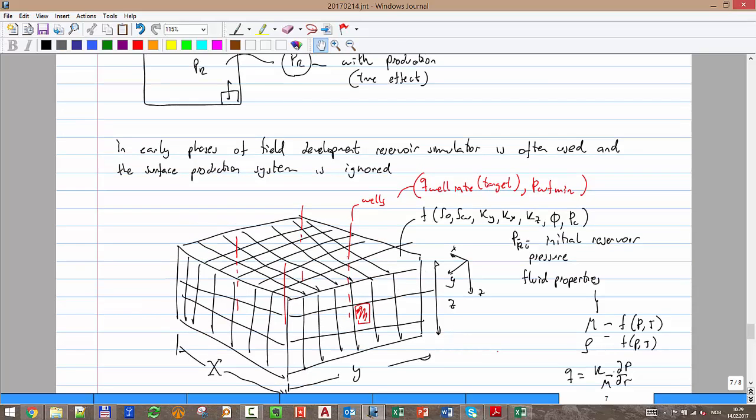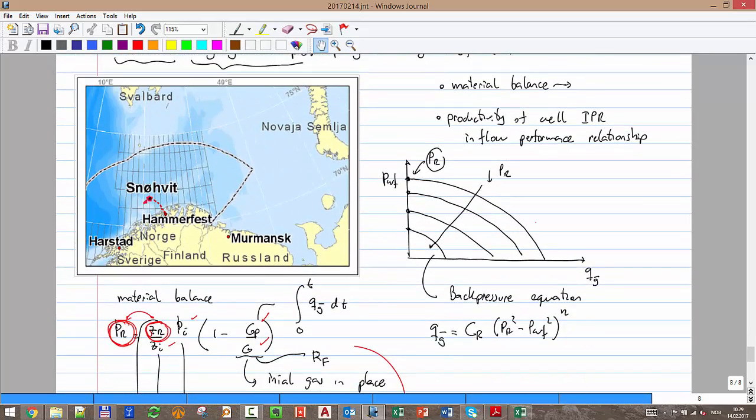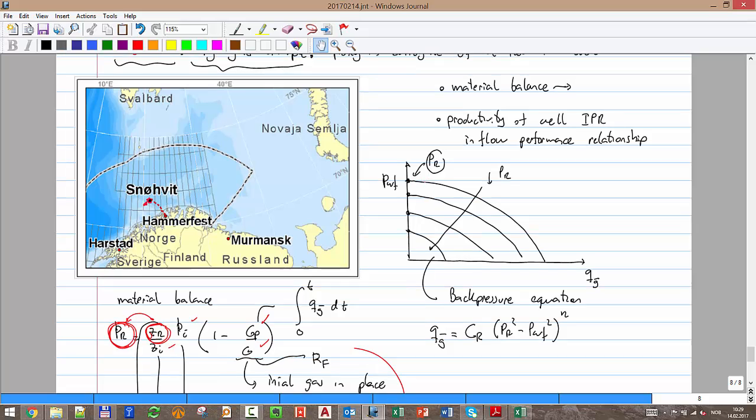Well, we are going to have a separate discussion on IPR if you feel like you need it. But at this point you just say, that's a curve. For a given reservoir pressure, I apply certain pressure at the sand face, and I will obtain certain rate. If you plot that, it will give you that descending behavior. And when you reduce reservoir pressure, it's just going to be scaled down and down and down.